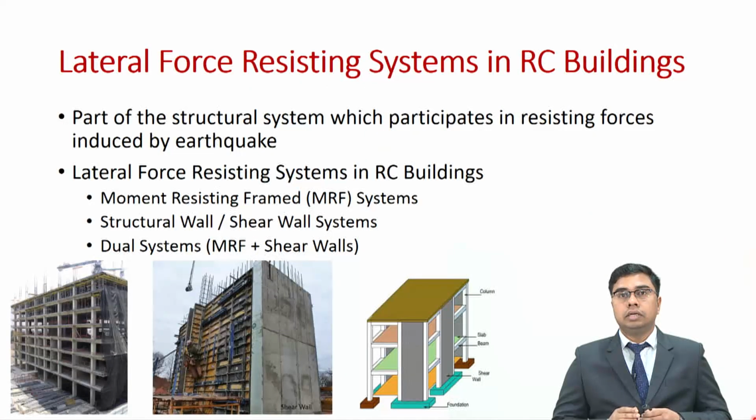In today's class, we will discuss various concepts and material specifications related to seismic design of RC buildings. As we proceed with our discussion into seismic design of reinforced concrete buildings, we need to first understand what the different lateral load resisting systems are in case of RC buildings. Lateral load resisting systems comprise those parts of the structures which participate in resisting forces induced by some lateral effects, earthquake in this case. In other cases, it might be wind as well.